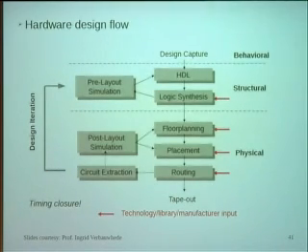Up to here, it's only structural, so there's no physical information in the implementation. Normally you write the HDL, do synthesis, and do some simulation. If it doesn't work, you go back. You go through several loops until you're satisfied, and then you give this implementation to the backend designers. They do floor planning, placement and routing. Eventually, they give you a circuit layout. That's how it is designed.